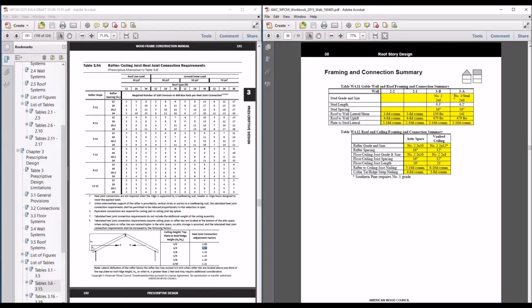And then on the vaulted end of the building, because we framed studs up, as you'll recall, those end up being second floor studs, we framed those up 12 feet tall. We only needed about a 6-foot stud. You could probably do that easily with 2x4s, but because all the other framing is 2x6, to keep that consistent, we went with a 2x6 in that gable end system. Those are all 16 inches on center.